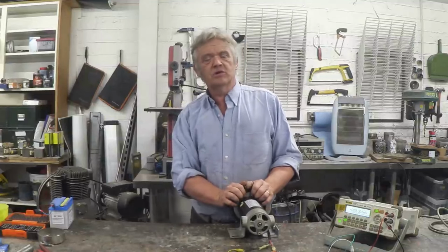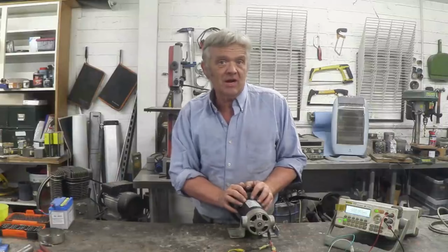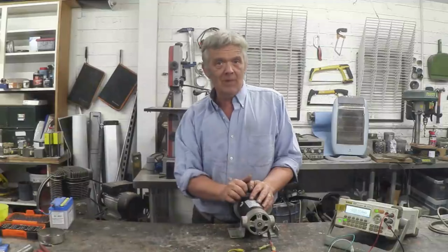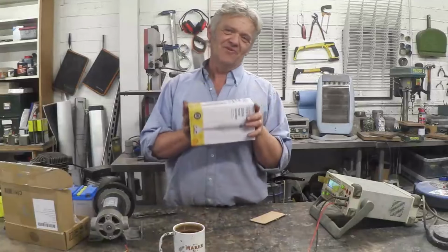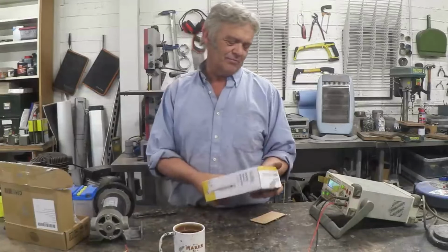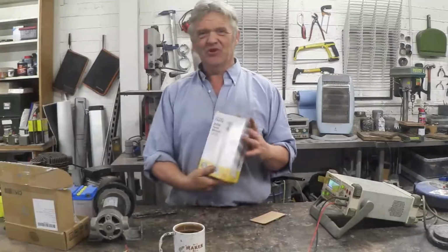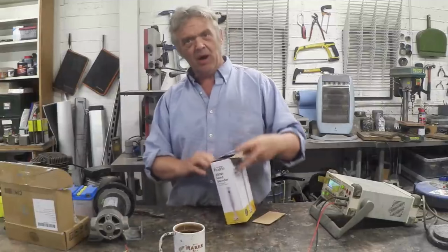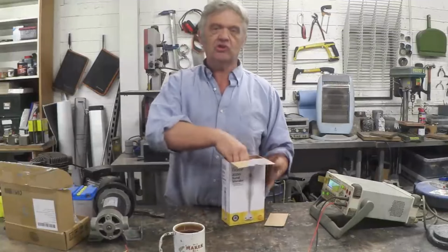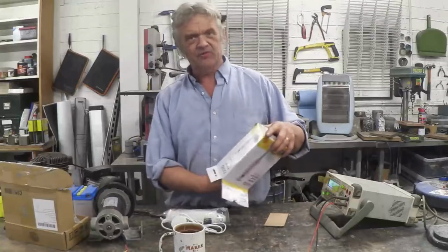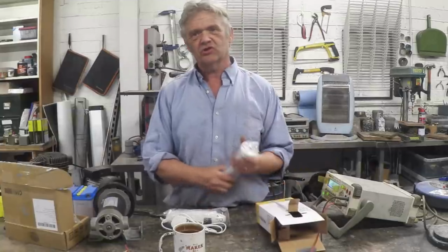Now, a quick word about efficiency. The efficiency of this thing that you make from scrap motors is extremely unlikely to be affected by the motor. The efficiency is going to be mechanical. It's going to be how well you make that structure that you attach to the motor for it to become a generator. I went down and bought one of these. It's a 200 watt hand blender from my local big box store, and it cost me £5.50. So as a blender, don't expect miracles, but when you take the blender apart, what you'll find inside is a DC motor and a rectifier bridge, and obviously an on-off switch. It astonishes me actually how they can make these things for those kind of prices.